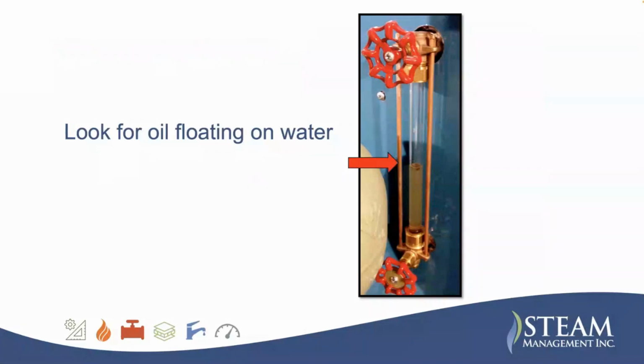The descaler did its job and it pulled the scale off, and the scale was the only thing holding the piping together. They had to replace all the boilers in the one building, and they had to replace almost a mile of pipe. So make sure you find someone that knows boilers, if I can say that.